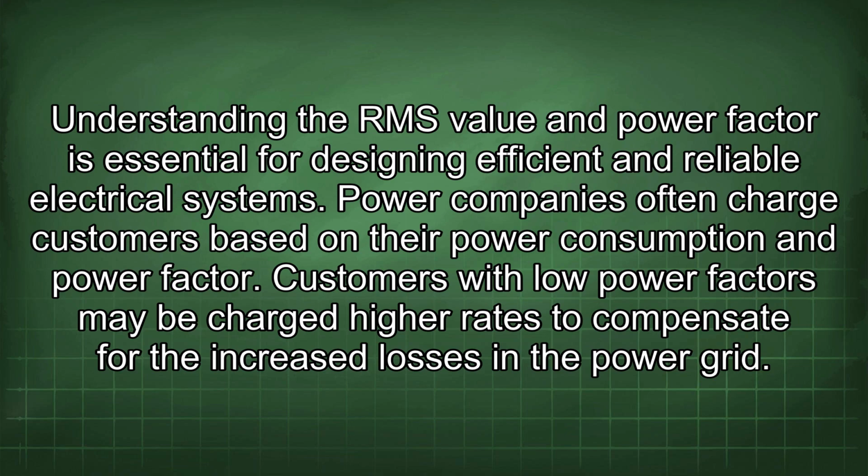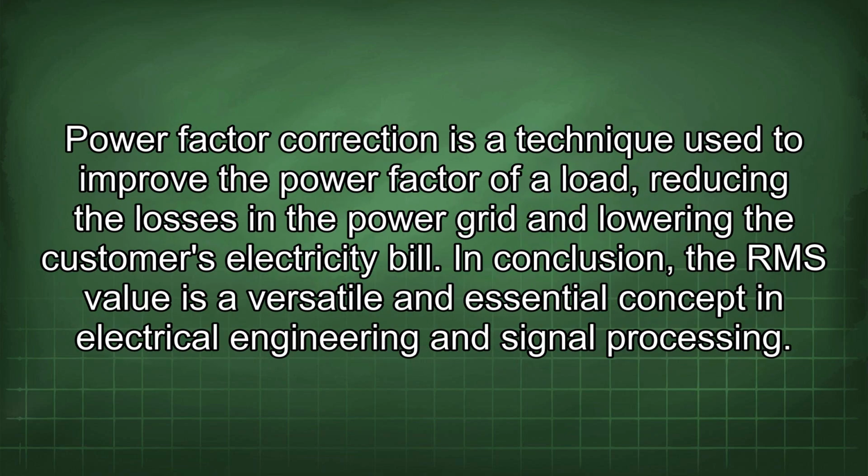Understanding the RMS value and power factor is essential for designing efficient and reliable electrical systems. Power companies often charge customers based on their power consumption and power factor. Customers with low power factors may be charged higher rates to compensate for the increased losses in the power grid. Power factor correction is a technique used to improve the power factor of a load, reducing the losses in the power grid and lowering the customer's electricity bill.